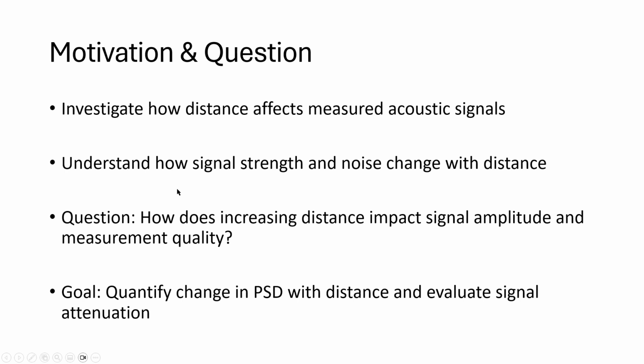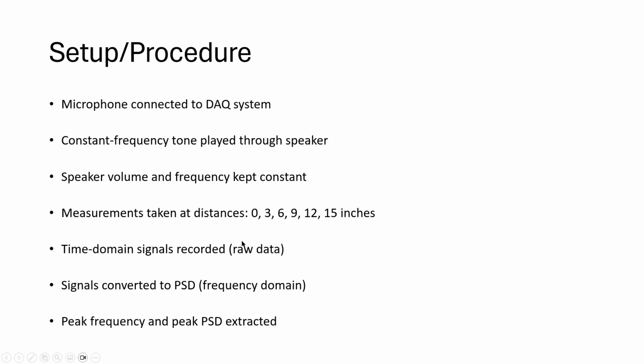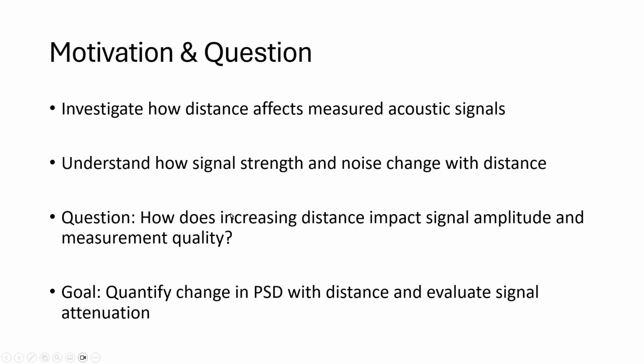Based on the validation test that I did previously, I chose about 1,000 hertz for my frequency, and the main question I wanted to answer was how increasing distance impacts the signal amplitude and the measurement quality. The goal was to quantify how the PSD changes with the distance, and then evaluate how the signal attenuates after that.